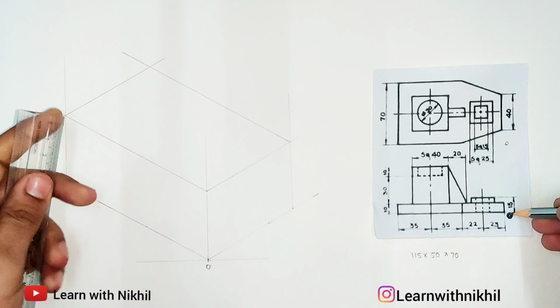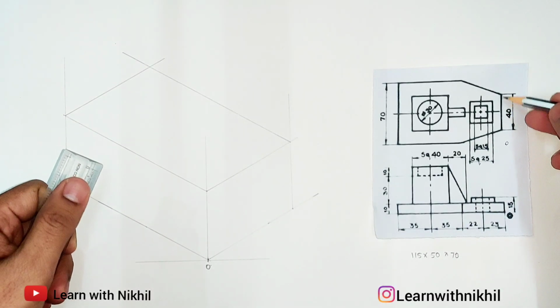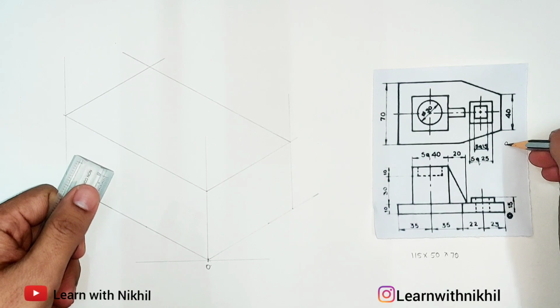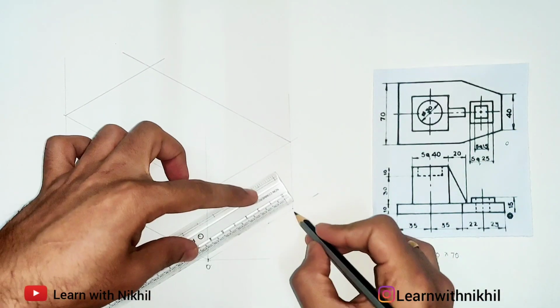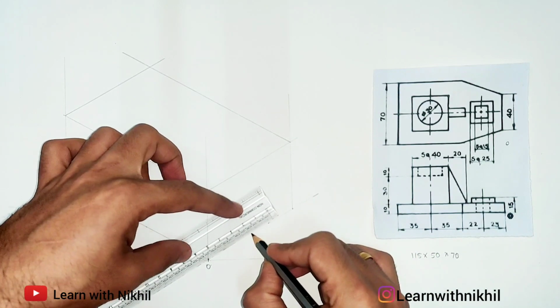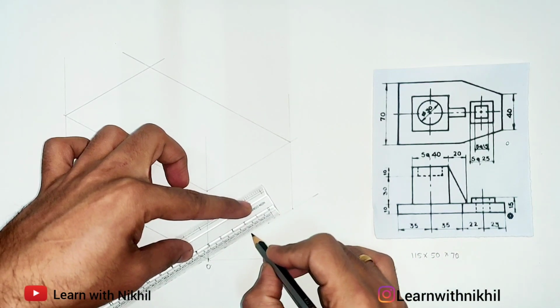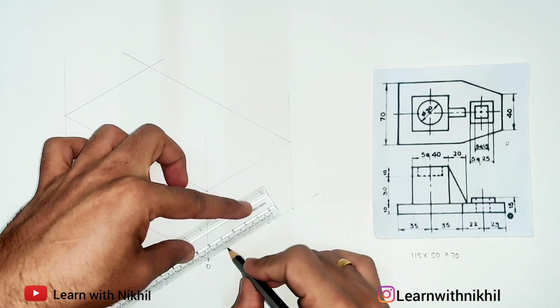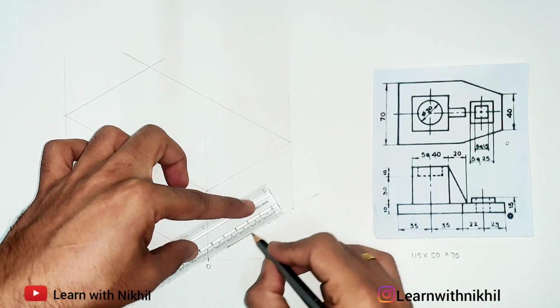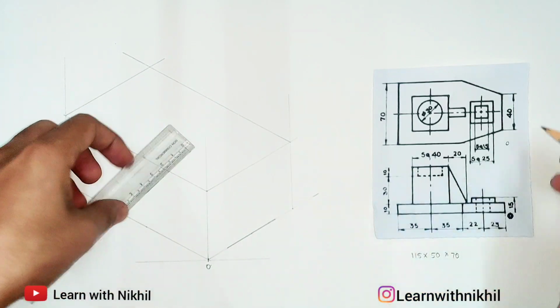So from point O, as you can see, first we have a distance of 40. Now it is not starting from the point O, it is from the center. So first on this line we will mark a point at the center, and from the center 20 millimeters on both the sides will give you 40 millimeter. So draw this line dark. So this is the line of 40 millimeter.